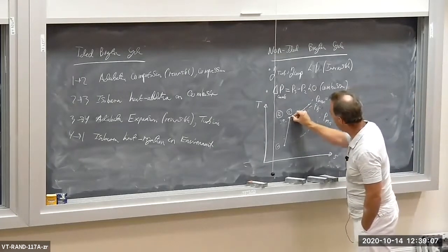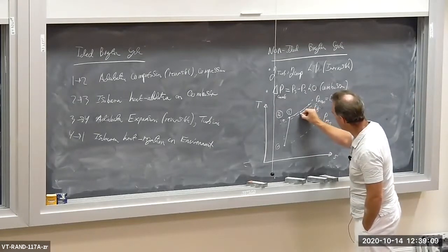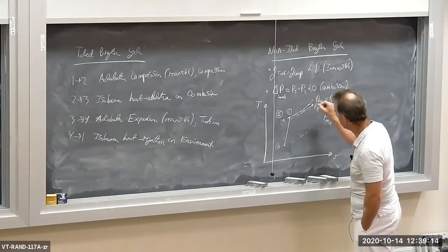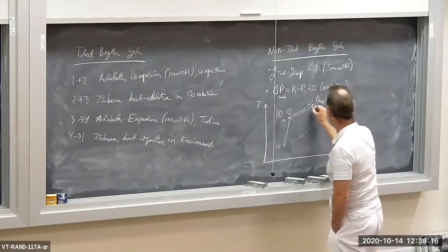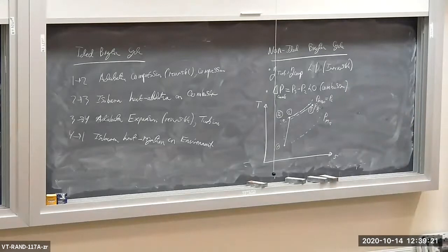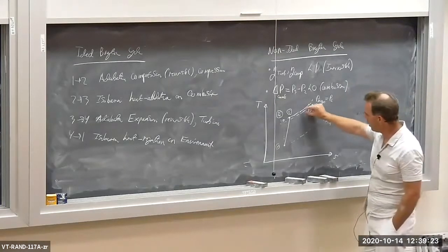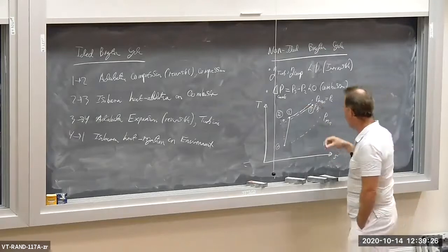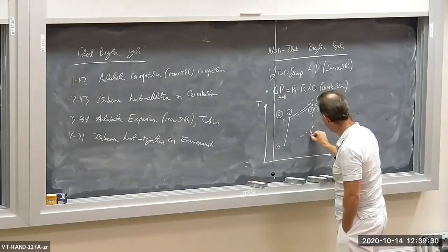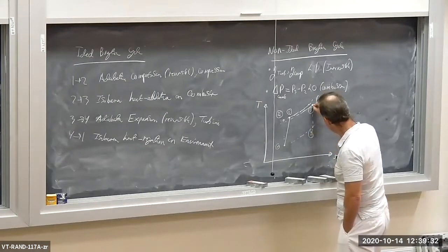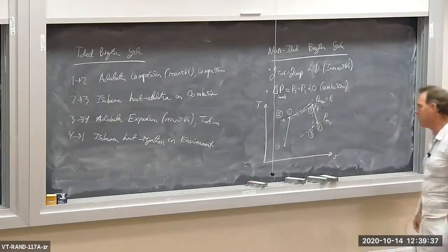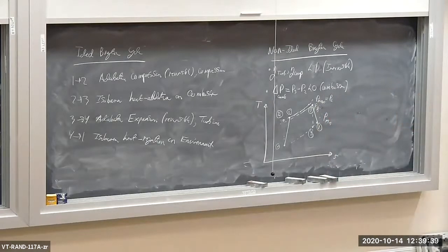We start off at a high pressure P max, and then we drop to a lower pressure in the combustor. And so this is state 3 here. There's state 3. Delta P across the combustor, delta P. And then we have the isentropic expansion process. So this is to 4 sub S. But the real turbine has some inefficiencies. So state 4 is actually a little bit to the right, okay?